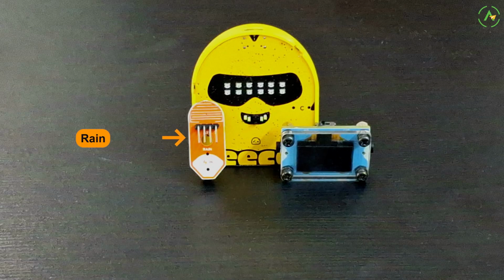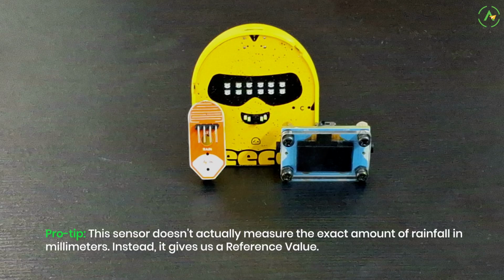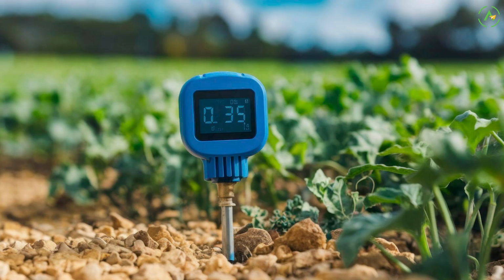Now let's look at the rain sensor. This sensor has a series of exposed copper tracks. When water drops hit it, the resistance changes. But here is a pro tip. This sensor doesn't actually measure the exact amount of rainfall in millimeters. Instead, it gives us a reference value. It tells the controller how much moisture is present, which we then use to trigger our code logic.